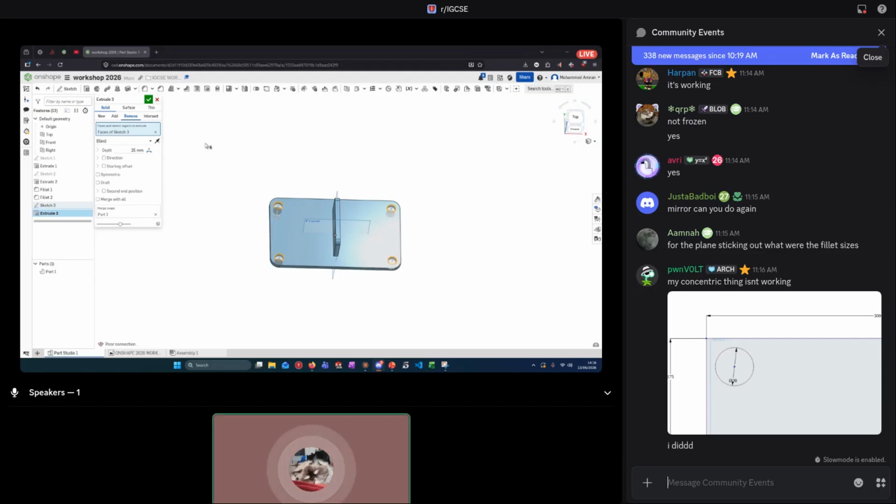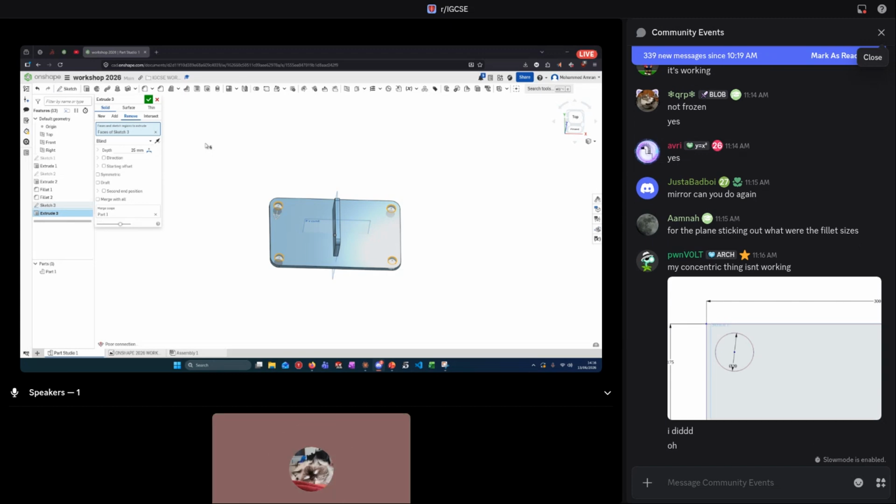You're going to create a new sketch. You're not going to edit the first sketch. Because right now, when you start editing the first sketch, it's going to take you all the way back as if you haven't done all the stuff that you have done until that point. Okay? So always create a new sketch. You want each feature to be on a new sketch. You don't want to create everything on one sketch, because then you have issues. Every time we're going to create a new sketch, okay?